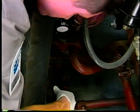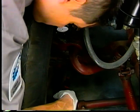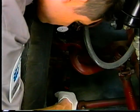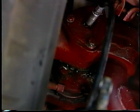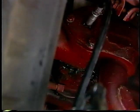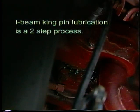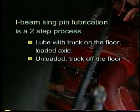Kingpins are tested with a dial indicator to check the vertical play in the kingpin as the knuckle is pried down. Any kingpin with excessive play must be replaced. When lubricating the kingpin bearings, make sure to continue greasing until some grease comes through the pilot bearing to ensure a thorough distribution of lubricant. I-beam kingpin lubrication is a two-step process. Lube with the truck on the floor, loaded axle, and again unloaded, truck off the floor.